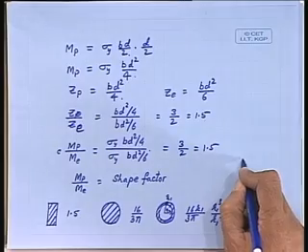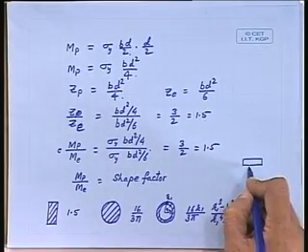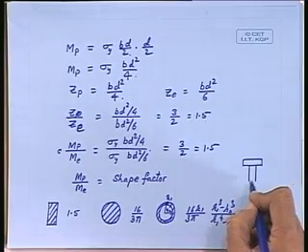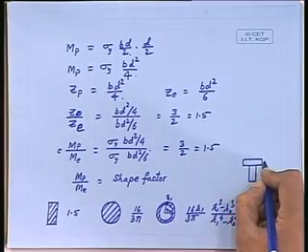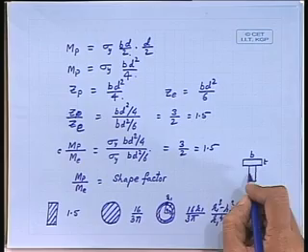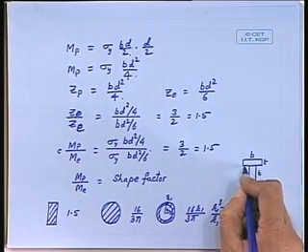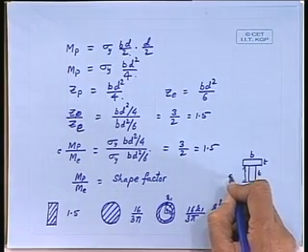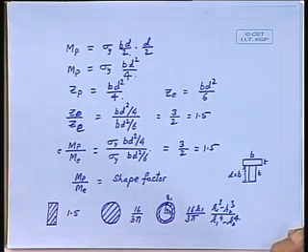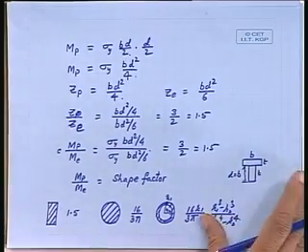You can try on your own a T section where you take this as B, this as T, and this also as thickness T, and this depth D is equal to B, and find out what is the shape factor of this cross section.